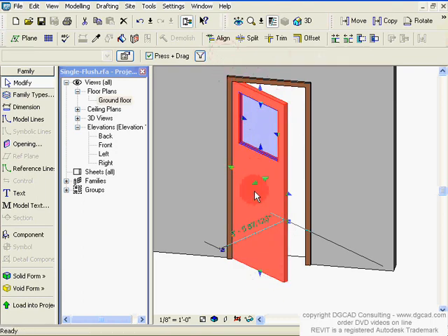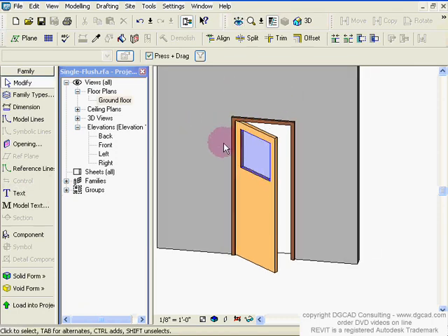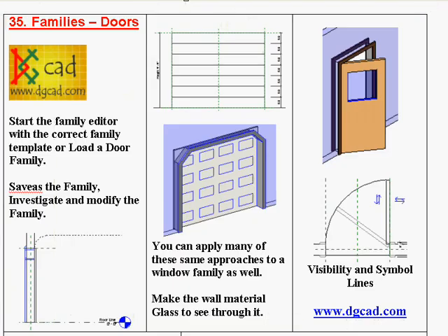Okay, so that works. And then of course you would go in and constrain, give this a height, go into this extrusion, and you want to go in and do a dimension perpendicular and call this width and call this height, so it'll change sizes when this door changes sizes. Positioning it and anchoring it back to that corner is a little bit tricky, so just a note on that.